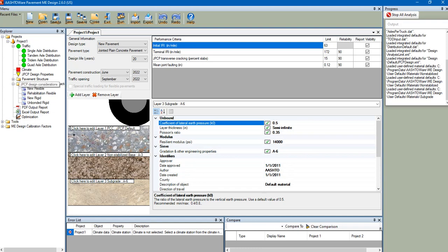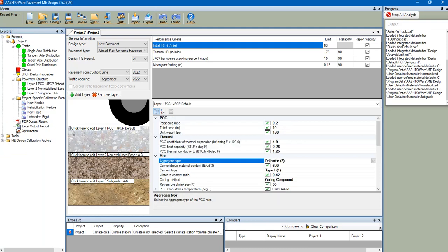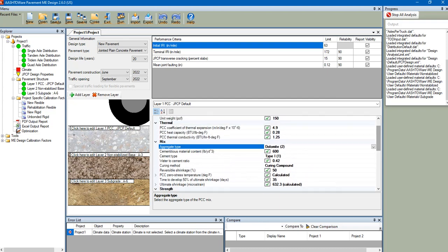So you can see there is some yellow line. Yellow means something may be wrong, it is just giving you a warning to check. Red means it is not input, it was not given as input, you need to input. Green means it is ready to go, but you should check all the information you are giving. So here, if I expand the pavement structure, I see yellow here. So let us check what happens, and check one more time. Everything looks good or no? To me, everything looks good.